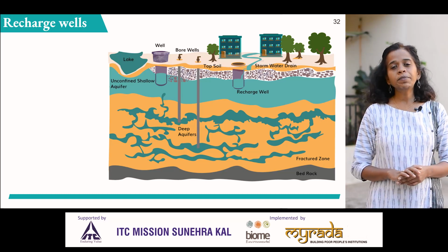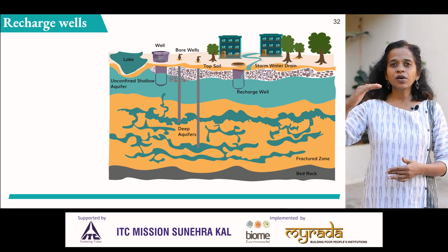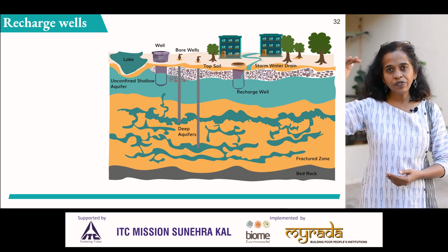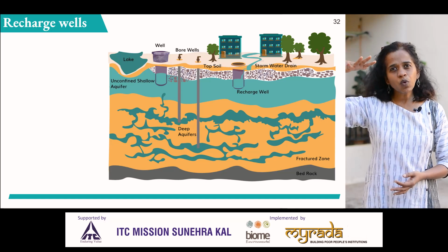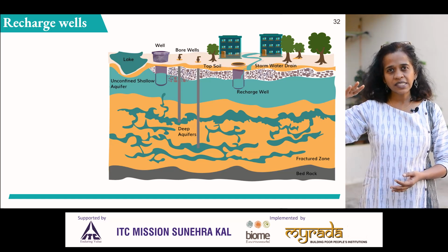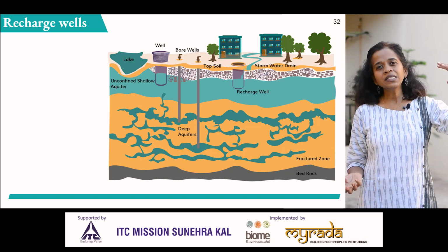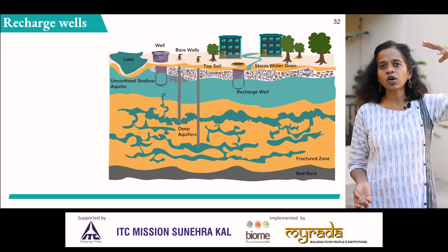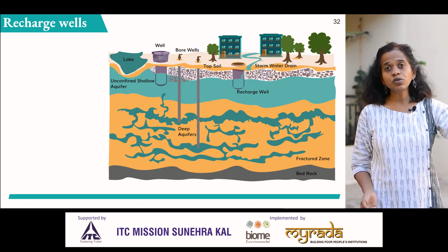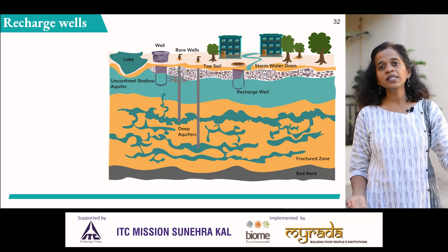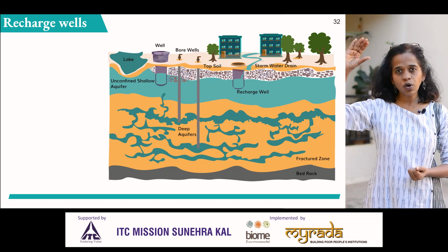Let's also look at Bangalore's hydrogeology. What we see is that from ground to about 5 feet below is what we call topsoil. Any rainwater or water that percolates into this depth is often lost to evapotranspiration. What that means is when the sun shines brightly, this water evaporates, the plants pull it up. So not a lot of this contributes to groundwater. It's not water that I can draw out again and use as a source of water. That's the top 5 feet.